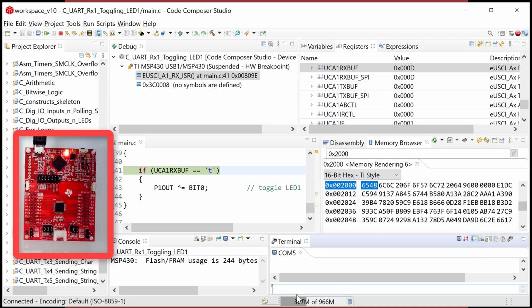So that's the difference in this terminal when I get into this toggle command inputs. When I send T down to the board, I'm not just sending T, I'm sending T and a carriage return. And so that's very important, because if we're going to type in this mode in the terminal, we've got to make sure that our program on the board understands that it's going to get a character followed by carriage return 0D, and then we have to account for that somehow in our program.